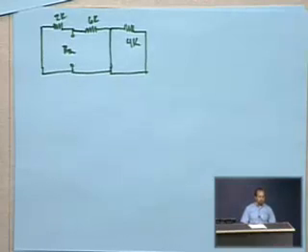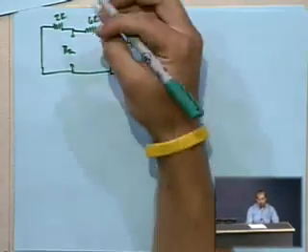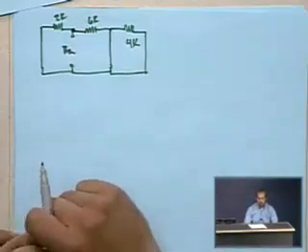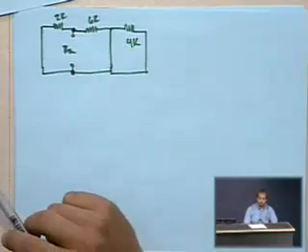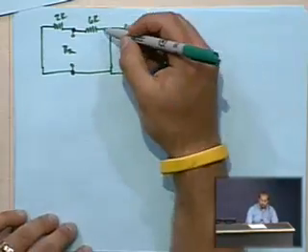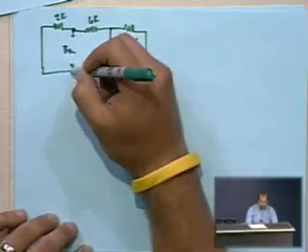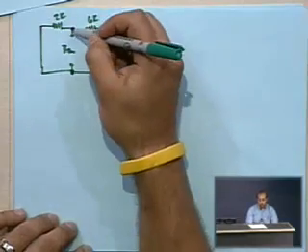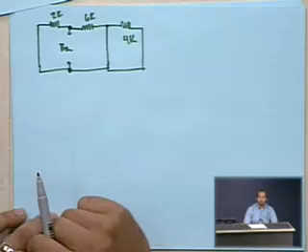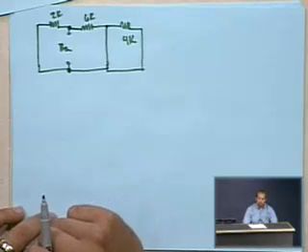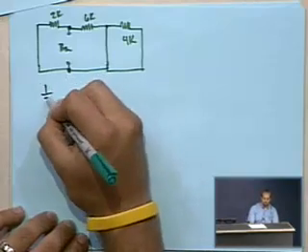But you have to realize that, again, we're looking at this from the terminals of the storage element. If you look at the two nodes at the end of each one of these resistors, you find that this node is this node. That's the end of the 6K resistor, and it's also the end of the 2K resistor, and they obviously share that one. So the 2K and the 6K are in parallel. And that is one of the hardest things to grasp about doing these problems.